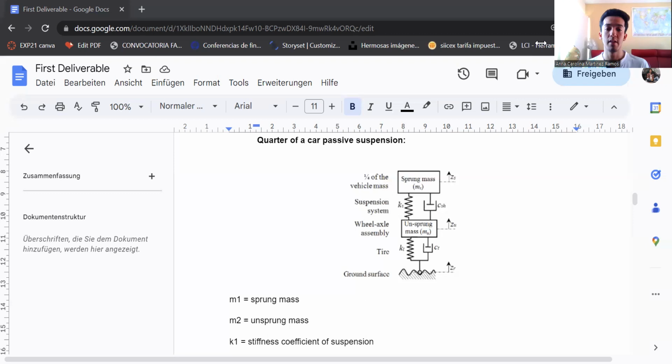Semi-active suspension is a type of automotive suspension system that controls the damping force of the shock absorber in response to input from the continually varying road surfaces. It is intended to approximately implement the active suspension with a damping force adjustable shock absorber. Semi-active suspensions may be implemented by skyhook control.